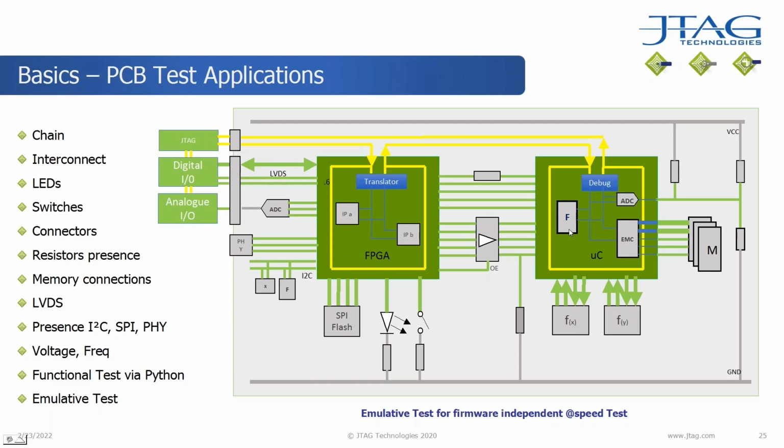Similarly, we could program embedded flash, or we can set up embedded analog to digital converters, and also digital to analog converters. So we can take analog measurements and create digital patterns and so on. Quite a lot of extra capability is offered by the system we call Core Commander, where we take control of the debug element of a device.